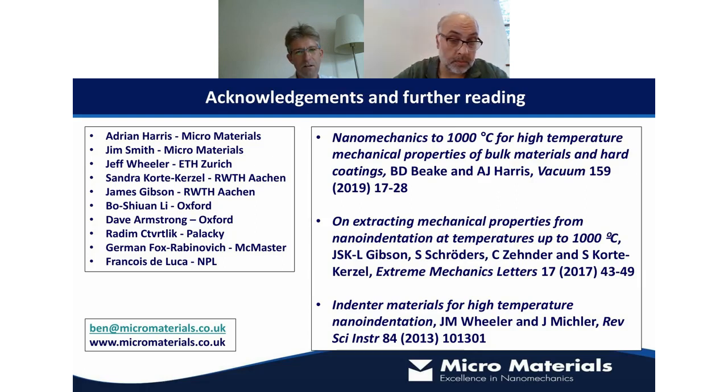If you're testing a material that retains a certain amount of stiffness at high temperatures, such as a coating we tested with diamond up to 900 degrees in vacuum, it had a modulus of around 400 GPa at 900 degrees, and it was about a 2% difference in that number by using the right elastic modulus in the calculation from reduced modulus to sample Young's modulus.